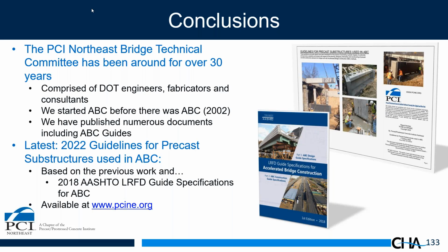The question came in beforehand, what is the proper foundation preparation for precast concrete footings? Yeah, like I said, the normal preparation if you're building on soil, whatever you would do for cast-in-place construction is appropriate. We have had cases we've talked about if you're on bedrock, you may have to do some pre-blasting and maybe even pour what we call a mud slab, which is a low strength concrete slab on top of the uneven rock surface to give you a table to work off of. New Hampshire DOT has done that before. So if you have a case of a spread footing on rock, a little more preparation, you probably got to create a relatively level surface to put your precast footing on.